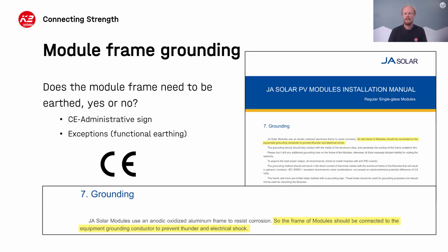This is not necessarily a level of quality, but it just says it's all been ticked off and met the appropriate requirements for the system. And what's interesting is that for an electrical product with a protection class 2, it says that an earthing conductor is not required, and it's also not permitted on such a device. So on one side, we have it saying it's not necessary and not required.